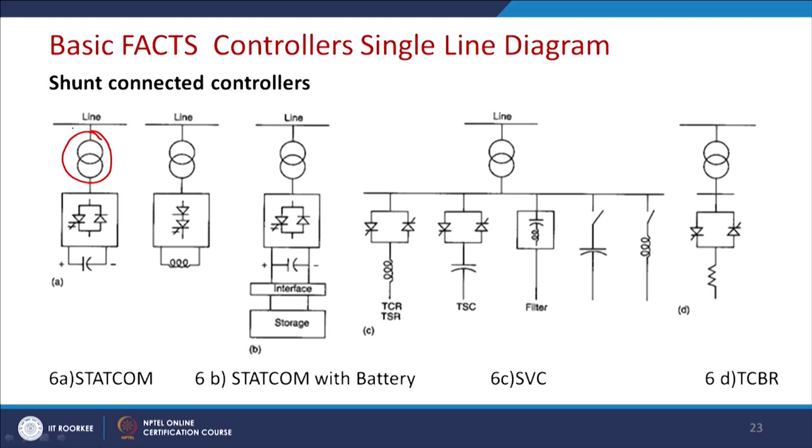but it can do that actively. The advantage is that it only has to feed the switching loss, and no prime mover is required, thus the efficiency of the system is quite high in this case. And when we use a voltage controlled current source inverter, then we shall use this kind of topology followed by a DC link capacitor.